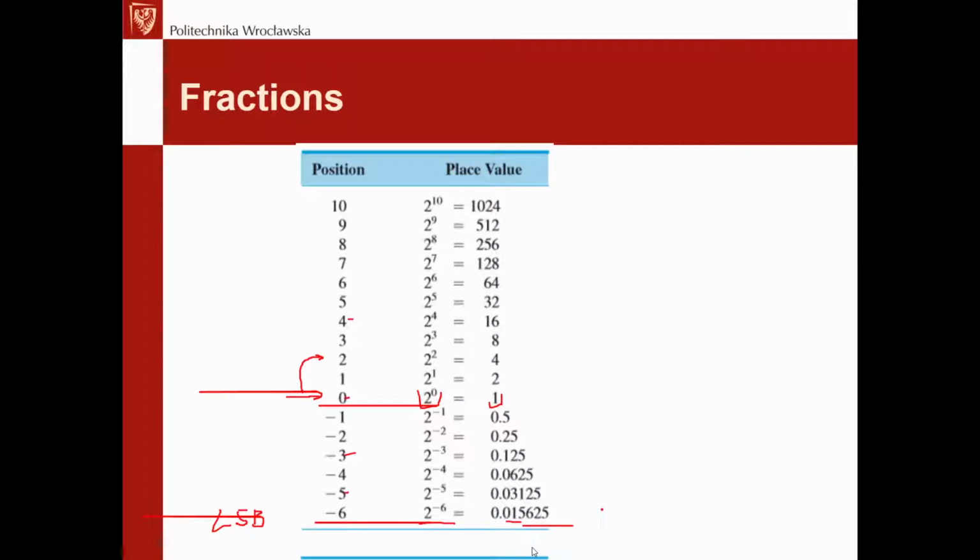So when I don't have any floating point unit available in a microcontroller, then I'm turning to fractionals, but then I'm using 32-bit fractionals, because their decimal point, when placed in the middle, allows coding numbers from 0 to 65K with a resolution of 1/65K.